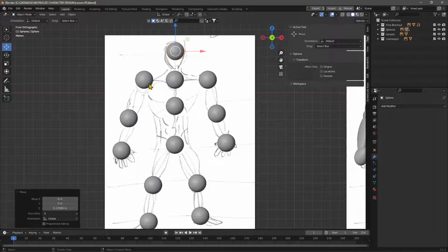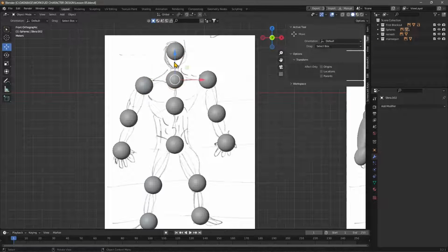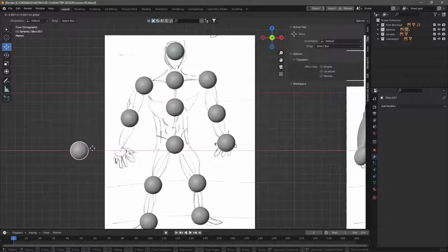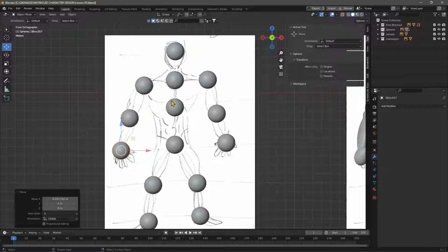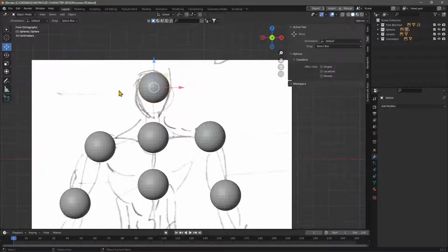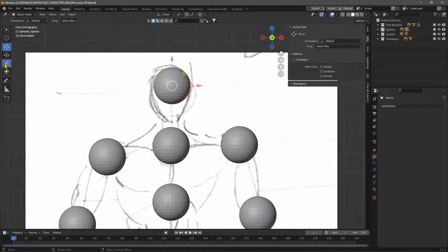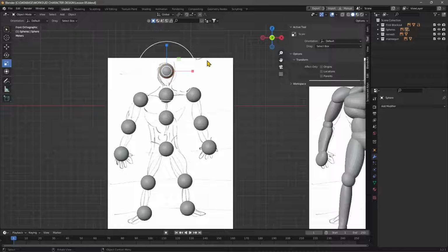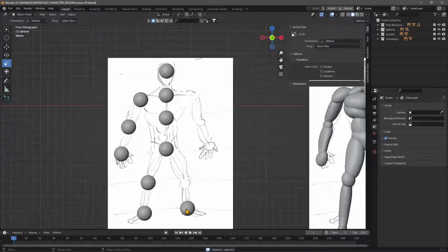But at first, I just placed these spheres on the corresponding circles that I have sketched out to create my model. So I created here the nodes and then the links using circles and lines. Here I'm going to use spheres and connection spheres, but I'm going to show you how you can adjust it a little bit. Now, when I first create the spheres, I can leave them all on one side, but then I can also delete one side because I only need one, since I'm going to use symmetry.